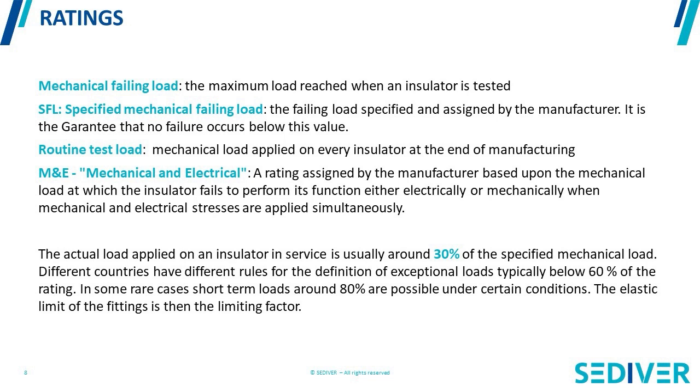But you have probably seen some testing: when you test 20 insulators, they don't all 20 fail at the same value. They are slightly scattered around an average value. And you need to be absolutely sure that when you calculate a standard deviation, the average failing load minus 3 or 4 standard deviations stays above the specified failing load.